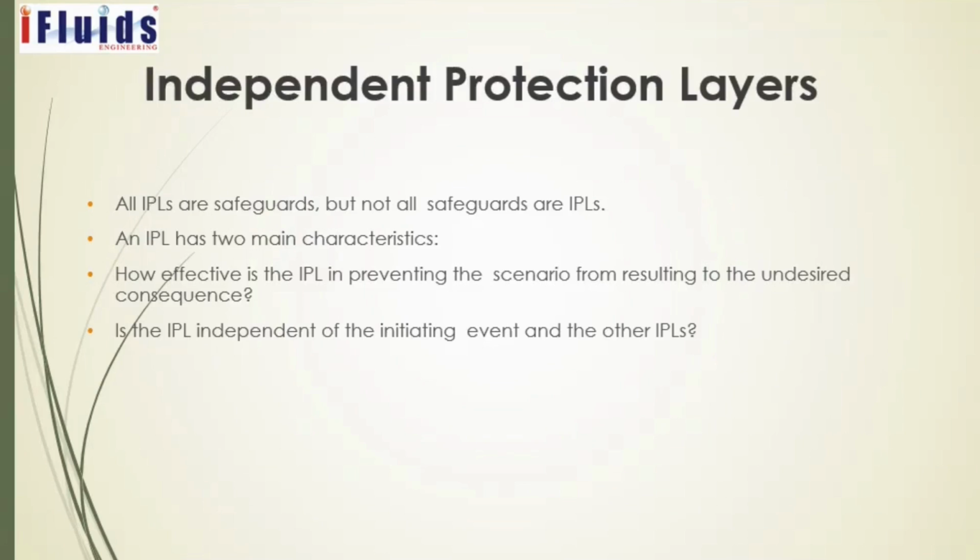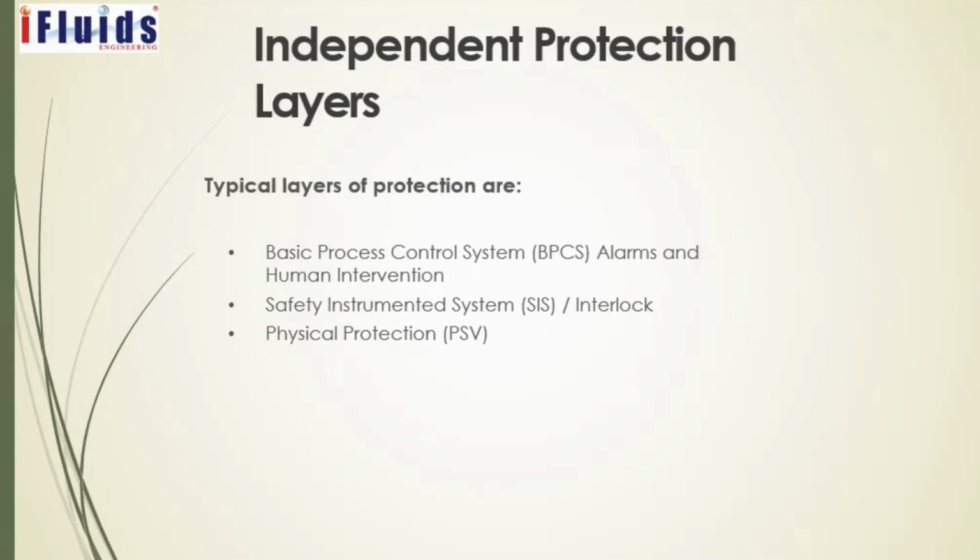IPL. All IPLs are safeguards, but all safeguards are not IPLs. Okay? An IPL has 2 main characteristics. How effective is the IPL in preventing the scenario from resulting in the undesired consequence? Is the IPL independent of the initiating event and the other IPLs? These things we have to see while dealing with IPL.